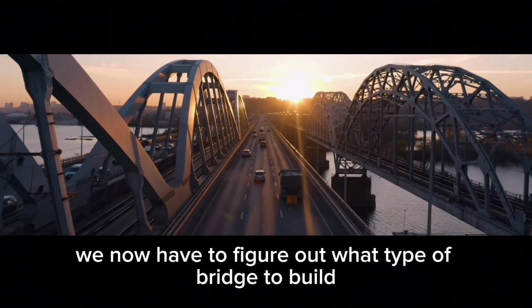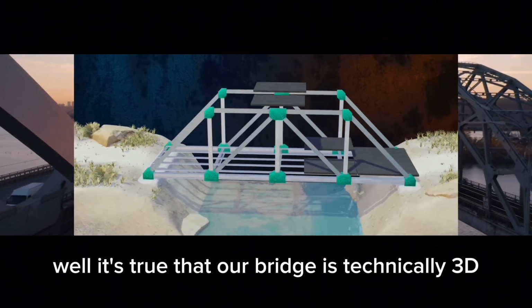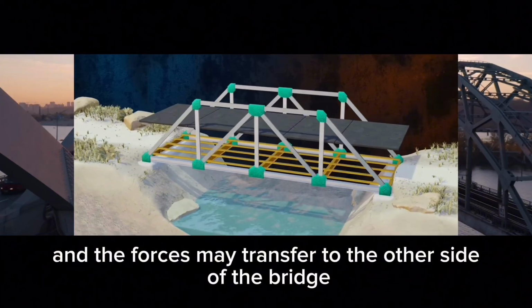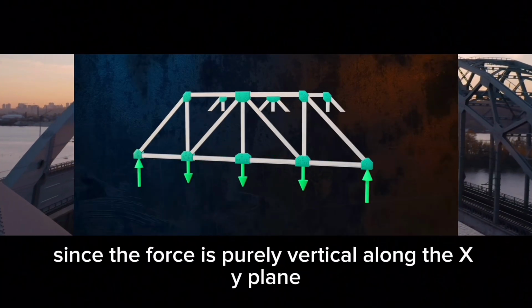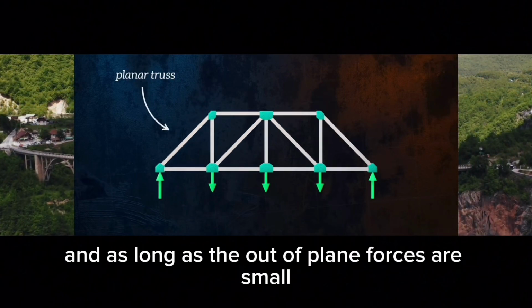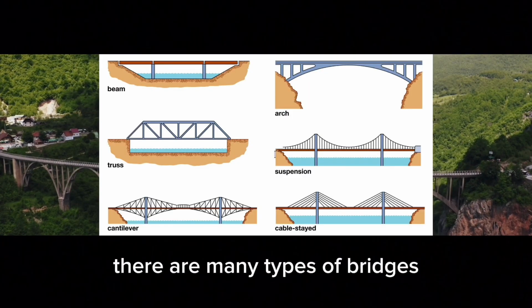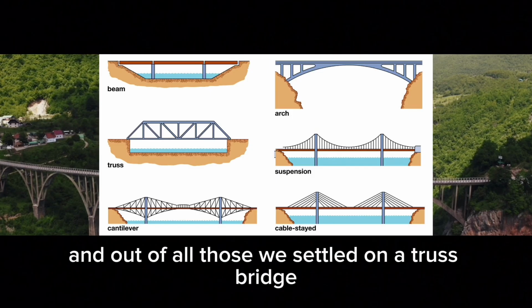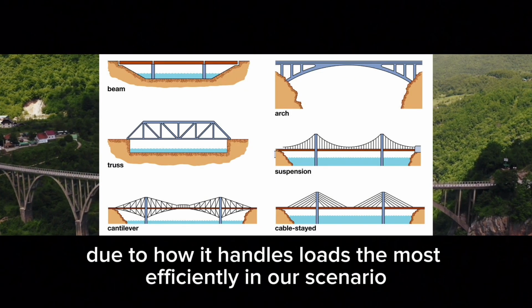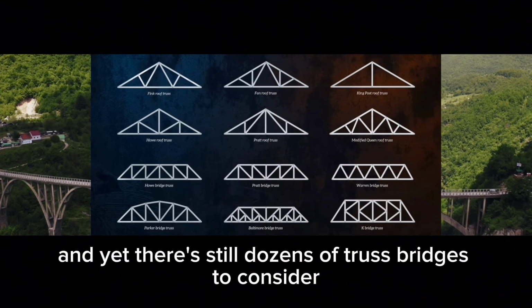We now had to figure out what type of bridge to build. It's true that our bridge is technically 3D and the forces may transfer to the other side of the bridge. We are assuming it's 2D since the force is purely vertical along the XY plane, and as long as the out-of-plane forces are small, the effect should be negligible. There are many types of bridges, and out of all of those, we settled on a truss bridge due to how it handles loads the most efficiently in our scenario, and yet there are still dozens of truss bridges to consider.